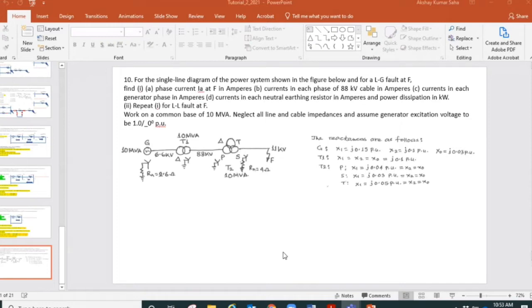So there are also 3 different configurations for each winding. One's delta, the other is star solidly grounded, and the other is star solidly grounded with a resistance. Okay, there is a little mistake in that statement. The third one you said, solidly grounded with resistance, is not correct technically. When you say solidly grounded, it means the resistance is 0. When it is grounded through resistance, it's not solidly grounded, it's grounded through resistance. Is that clear? Yes, I understand now.